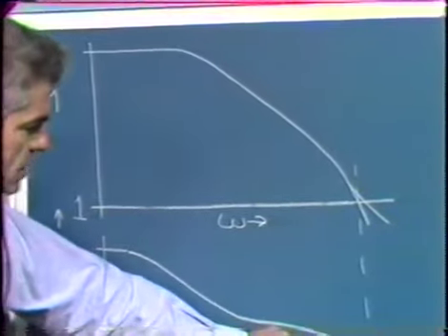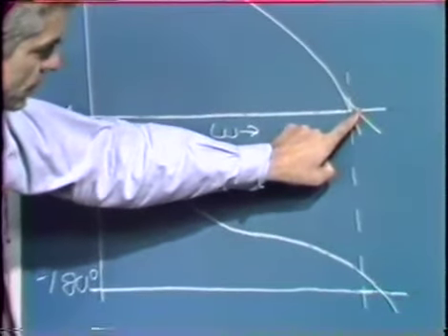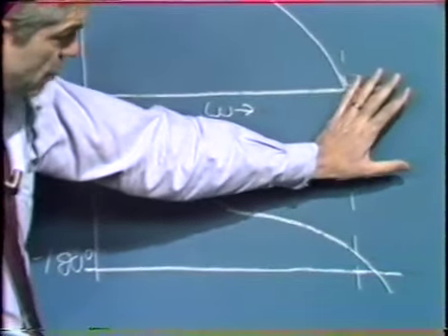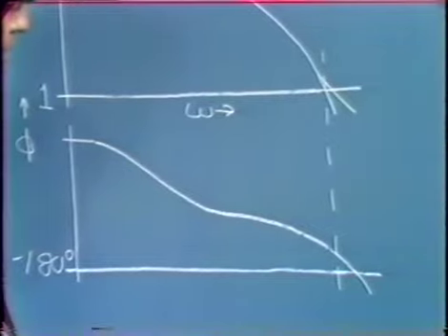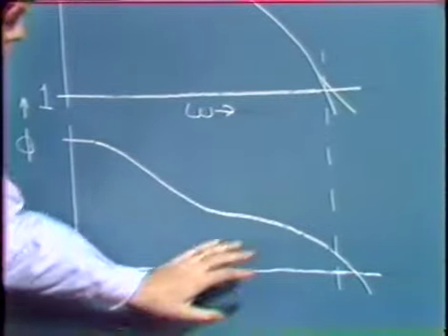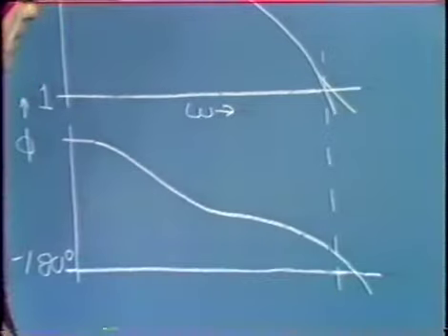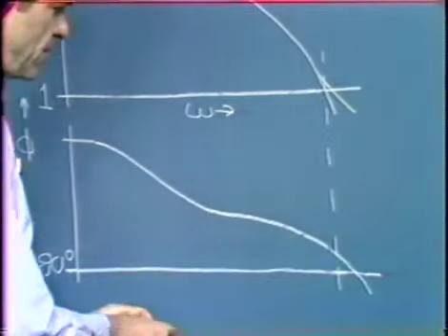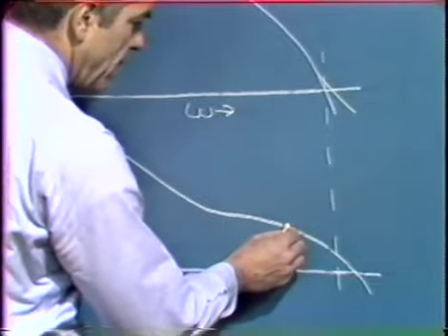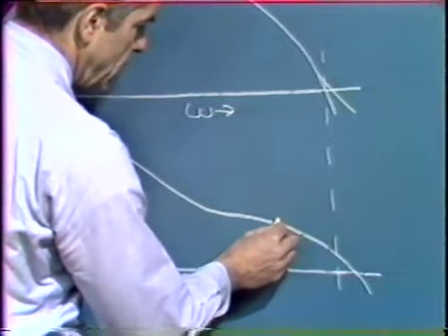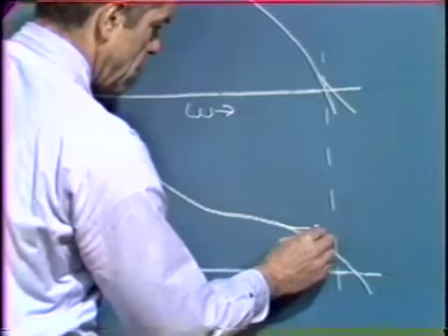What we depend on is the fact that in this region, before the magnitude has increased appreciably, which would lead us to much higher crossover frequencies, in this vicinity we get appreciable positive phase shift out of our lead type transfer function. And so the hope would be that the modification made to the angle is something like so.